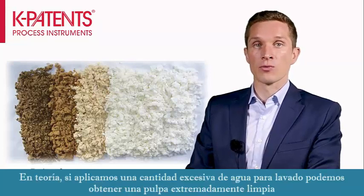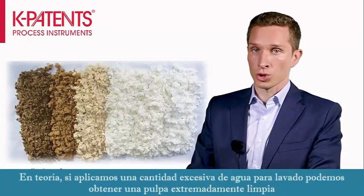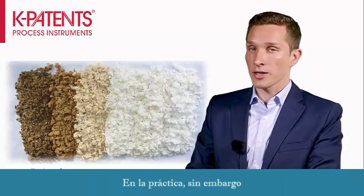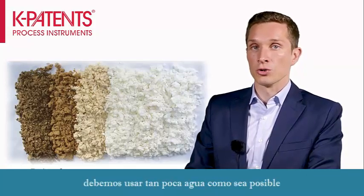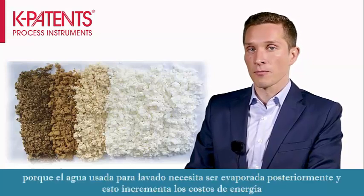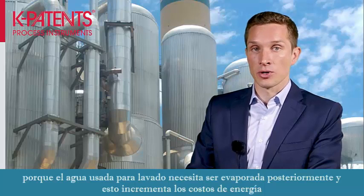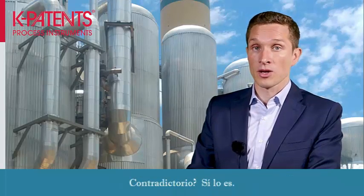In theory, if we apply an excess amount of water for washing, we get extremely clean pulp. In practice, however, we should use as little water as possible because the water used for washing needs to be evaporated later, and this increases the energy costs. Contradictory? Yes, it is.